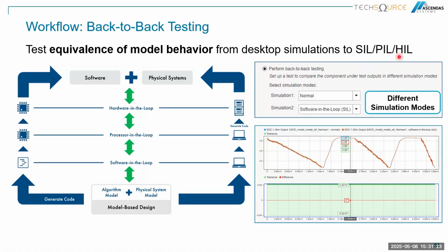So for this one, we have this workflow. At first, you just create the model in Simulink. Because we have tools called Embedded Coder or Simulink Coder, you can convert this Simulink model to C or C++ code. You can deploy it to the embedded board and test it, like processor in the loop, for example. This is the workflow of how model-based design supports the AI workflow here.